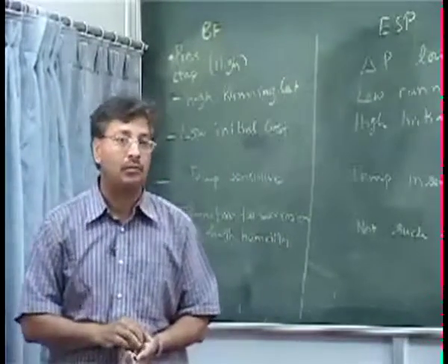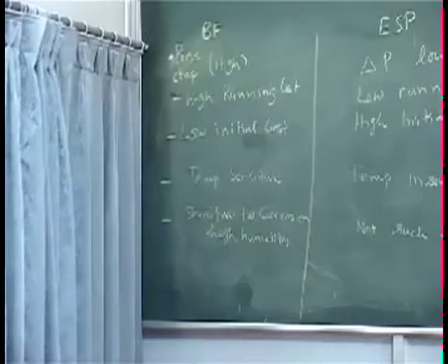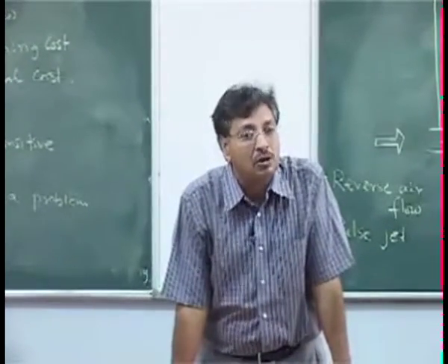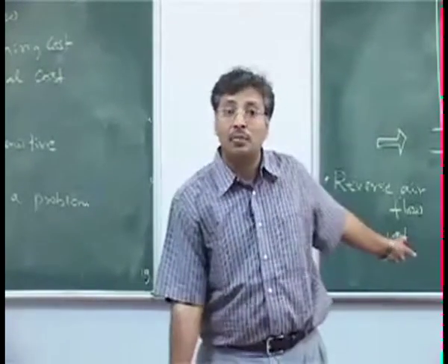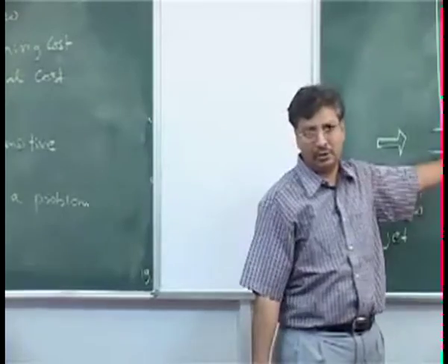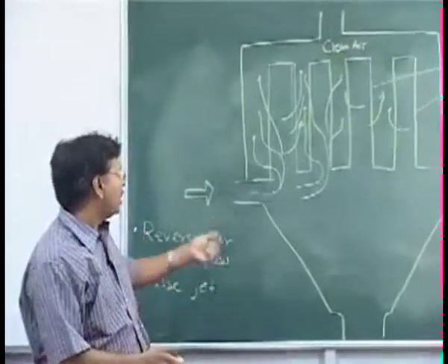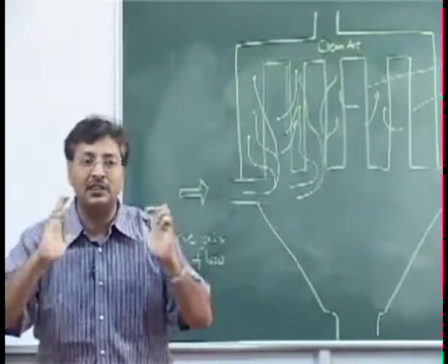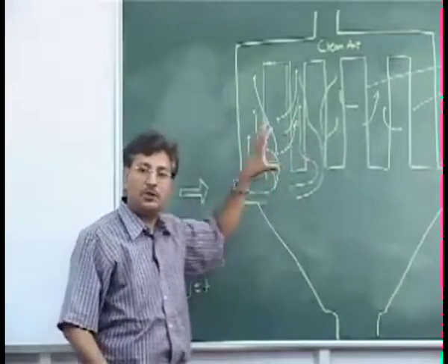Running cost in the case of ESP, there also we can consider it high because of the power requirements. See, comparatively, again, we are not giving the numbers, the question is well taken, but the running cost of this one is not so high, depending on the power plant you are dealing with. That cost is very small, but here the cost of blowers, and the pressure drop, is really very high. The order of the pressure drop difference is so high that I don't remember the numbers. In the ESP, there is no obstruction to the flow of the air, it just simply travels as if it is traveling in a duct, and here every little thing has to go through the filter. So the pressure drop is enormous here.